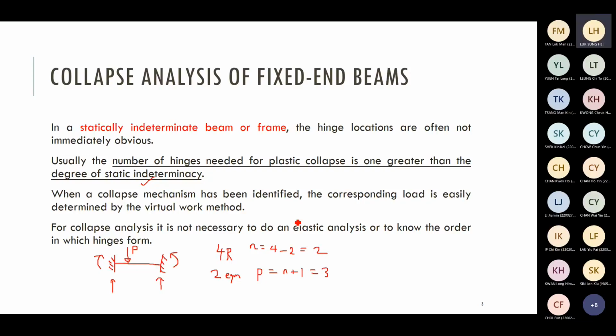But personally, I seldom use it. Personally, I just add hinges continuously on the structure. After adding 1 hinge, it's still stable. And then I add another. After adding 2 hinges, it's still stable, right? It's just like a simply supported beam. For a simply supported beam, you can add 1 more hinge. For myself, I normally add hinges continuously until I observe an unstable pattern occurring. I seldom memorize this kind of rule; maybe sometimes it's useful, but I seldom use it.